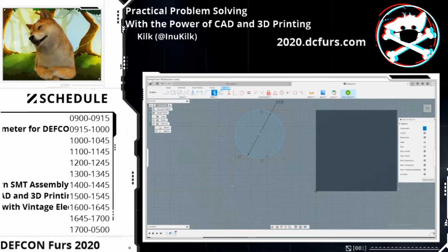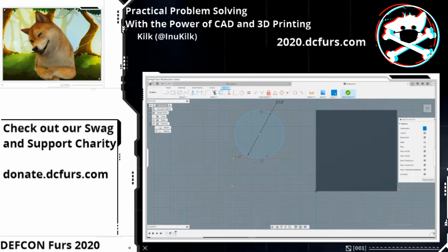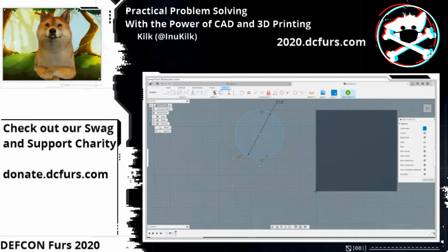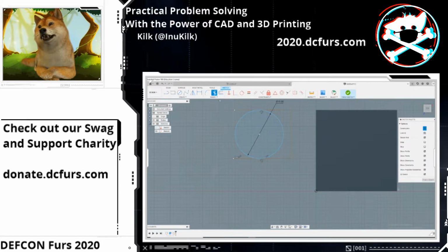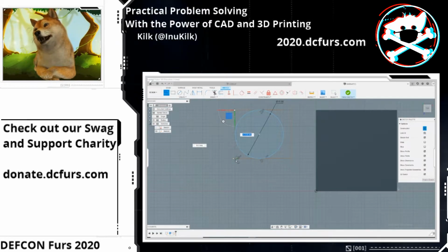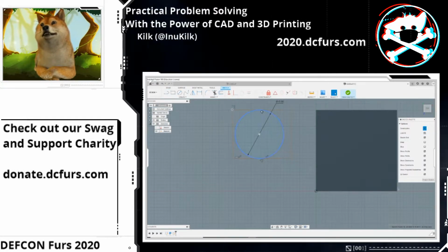This is really useful. Sometimes if you make sketches and the line isn't segmented correctly, it will usually not fill it and you won't be able to extrude it. So what you have to do is go back into your sketch, trim it, and then refill it like this. So now this is complete. This is a cube and these 2 points are tangent.